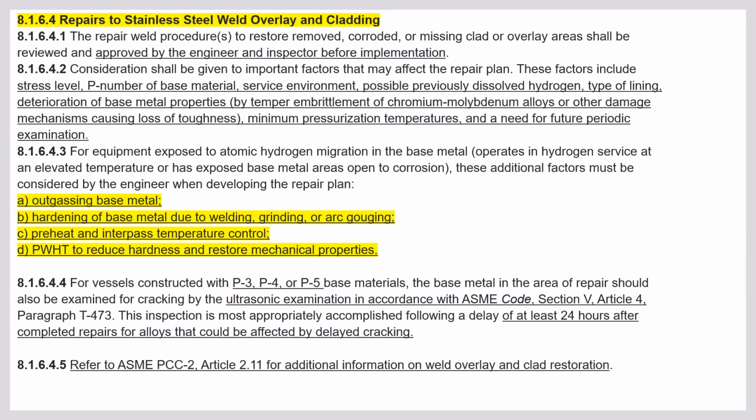Now, repair of stainless steel weld overlays and claddings. How will stainless steel weld overlays and claddings be repaired? The repair weld procedure to restore removed, corroded and missing clad or overlay areas shall be reviewed and approved by the engineer and inspector. So the engineer and inspector have to review that.